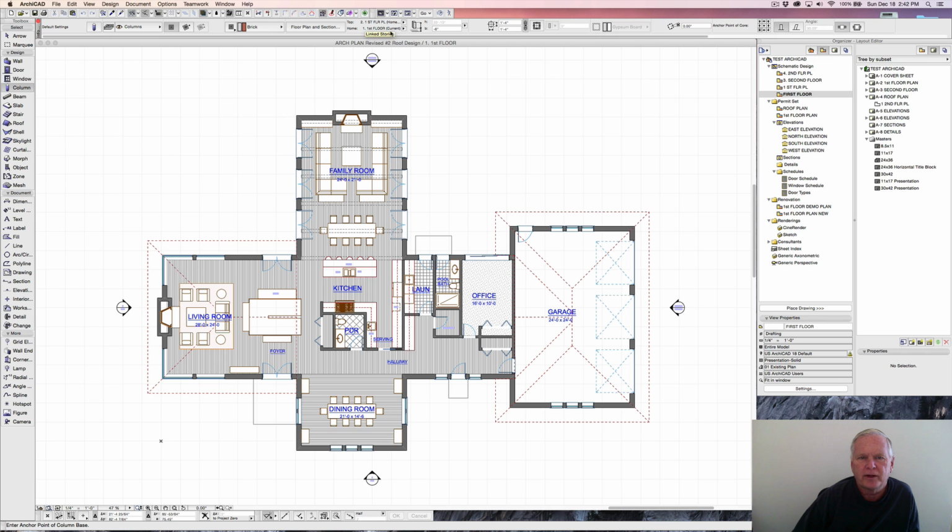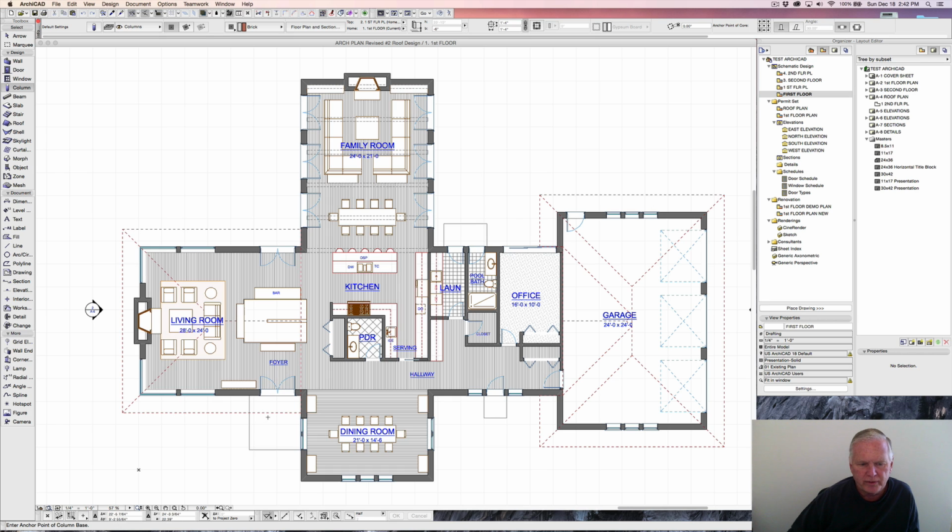And we are currently on the first floor at -6. That is the level of our porch out here that we had previously put on, and our size of our column is 1.4 by 1.4. Had that in already. And so we'll go ahead and, one other item, the anchor point for putting in this column is going to be this front corner, so that when I go to this front corner right here and click, I have the column put in for us.